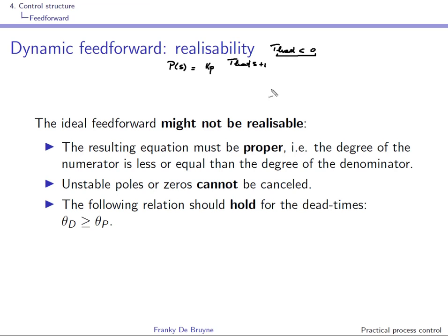So we have here a system with an inverse response, right? We have two time constants, let's say. So Tp1 over here and Tp2 S+1, right? And the disturbance dynamics is simply a first order dynamic, so TdS plus 1.